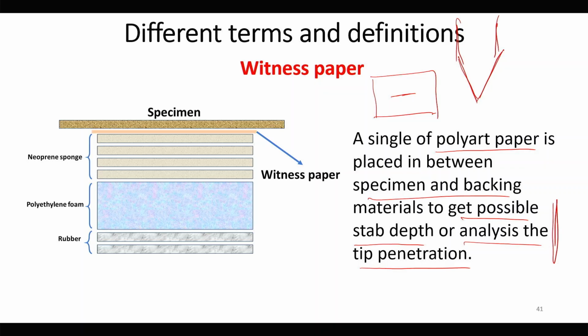It will penetrate through the back of the specimen, immediately through this witness paper, and depending on the length of the cut, we can calculate the depth of penetration, the depth of puncture.